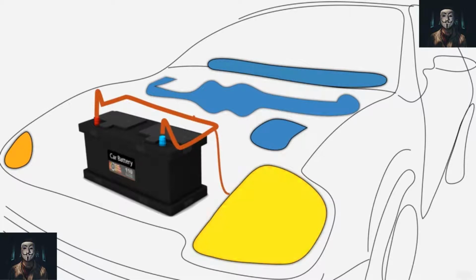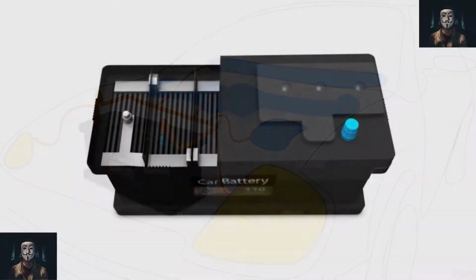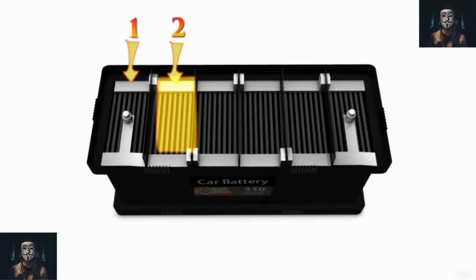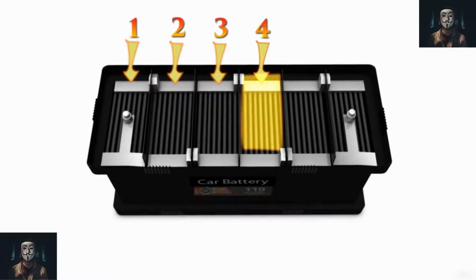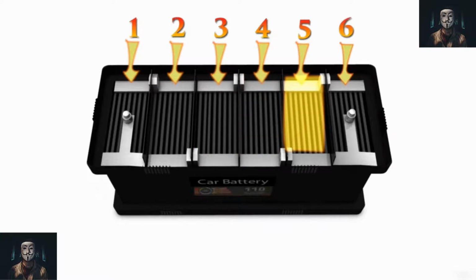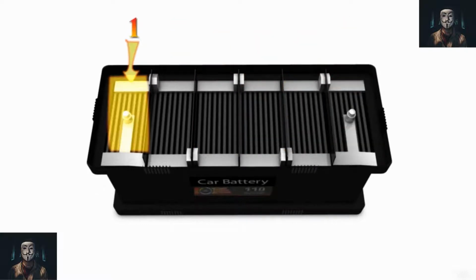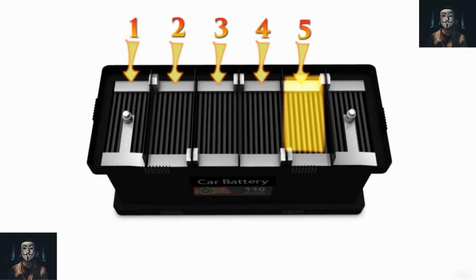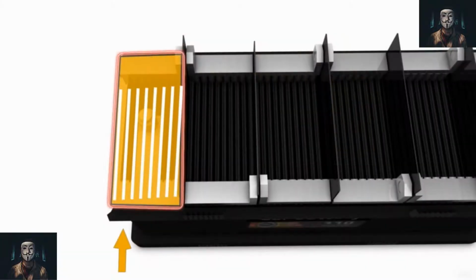Only distilled or specially produced topping up water should be used. Tap water is not suitable for topping up a battery. Acid should never be used, as this will strengthen the acid solution and alter the chemical reactions. Most modern batteries, however, include vapor traps and other features to minimize water loss and therefore need little or no attention. The electrolyte chemical composition changes with the state of charge.